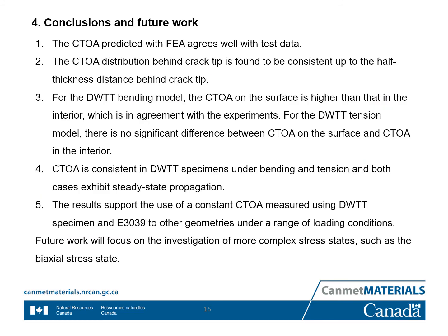From this research, we can draw the following conclusions. First, in this research, we used a state-dependent damage mechanics model to investigate CTOA. The CTOA predicted with the finite element analysis agrees well with the experimental data. Secondly, the CTOA distribution behind the crack tip is found to be consistent up to half the thickness distance behind the crack tip. At a distance larger than half the thickness, the CTOA starts to increase gradually.